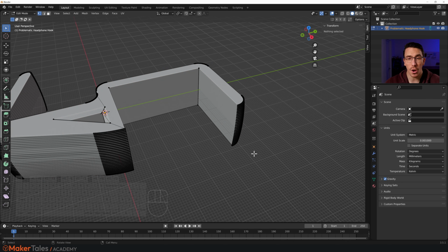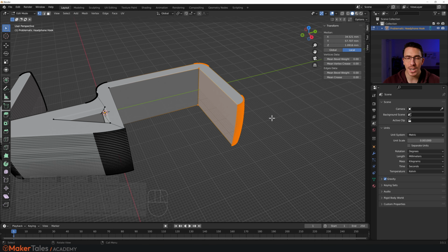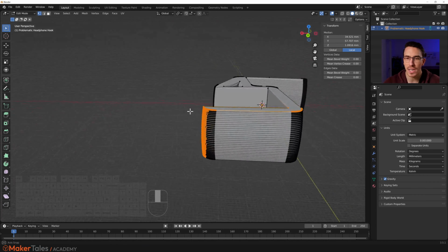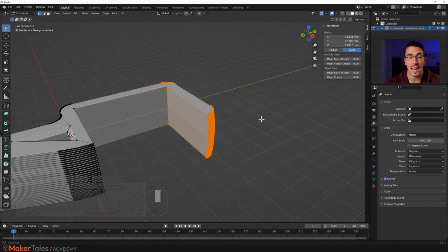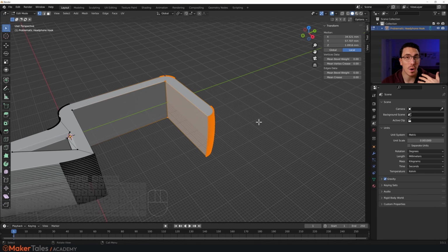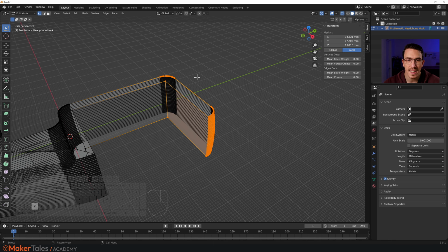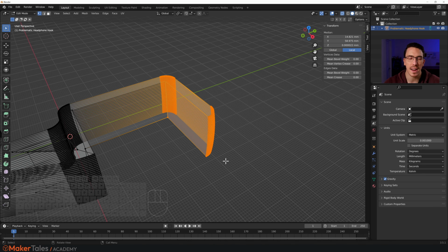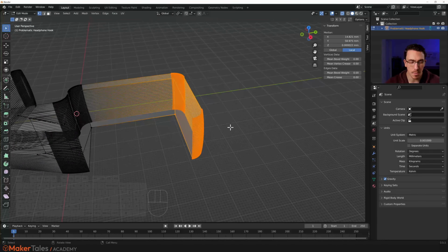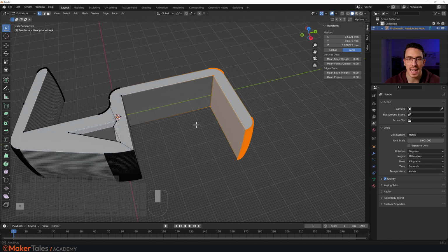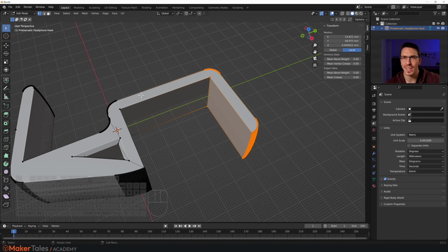I want to move this top part here. You might think that you can just left click and drag, but remember, mesh is solid. You cannot select through it. To be able to select through it, we need to make it invisible or have some sort of X-ray effect, and that again is with the toggle X-ray. So that is Alt-Z, and this way I can select everything there with confidence, and I have that all selected. I'll press Alt-Z once again to deselect that, and now we can use the 3D cursor and snap all over the place and use active elements and all the rest, but how about we just use CAD transforms once again?